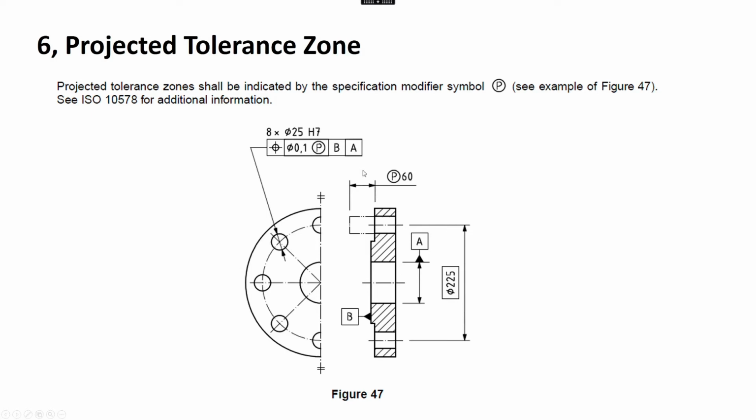The problem is with the way that the GD&T works, it's the squareness that gives you the problem and why projected tolerance zone is so good. So for example, these holes here, if these were a lot longer, you'd probably understand the problem. So if we put a positional tolerance on this particular hole, the positional tolerance works from a circle at this location and a circle at this location, and it's the center line of that. So if we produce this hole and it's within tolerance, but the diameter is 0.4, 0.4, and it's going from extreme to extreme.